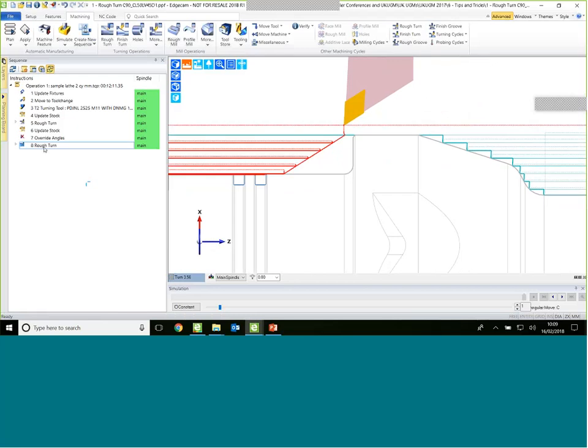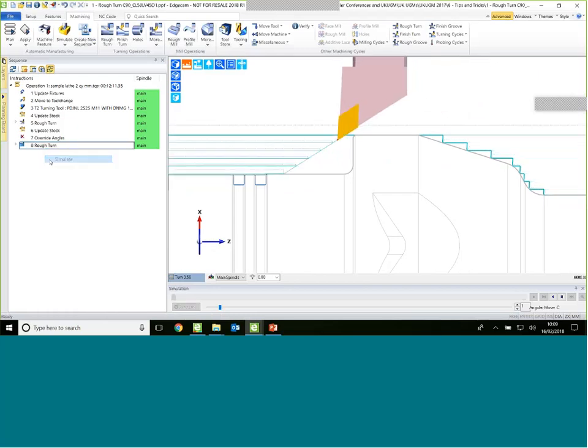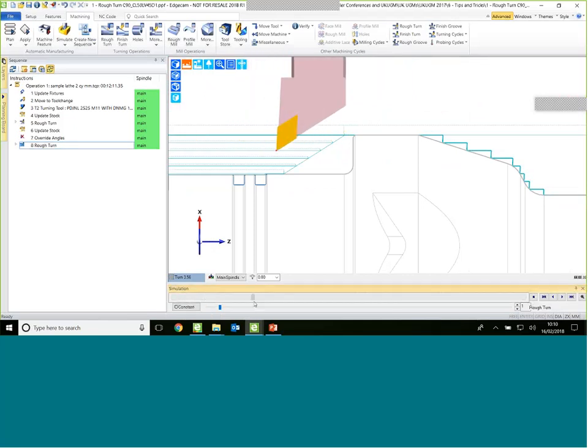Okay, so as we watch this tool descend into the cut, it's not at this stage perfect. What would be perfect is that as we descend into the cut, we're not going to scrape the back of that tool. Okay, it's probably going to judder and certainly cause a lot of tool wear.